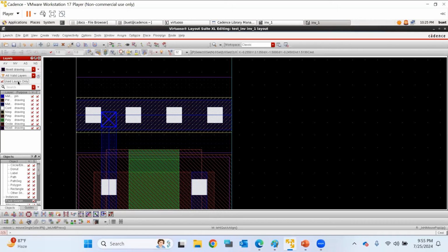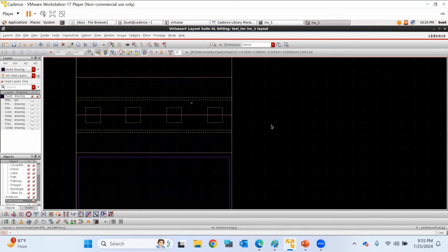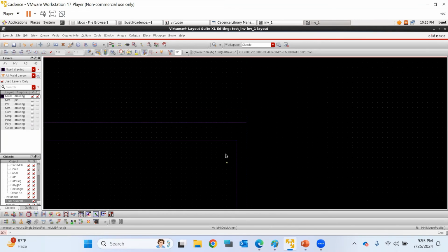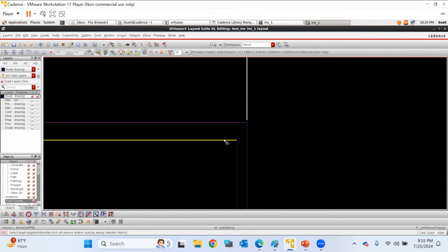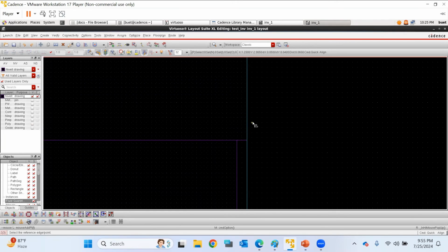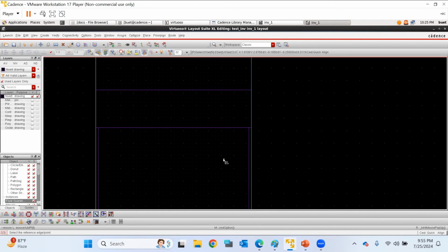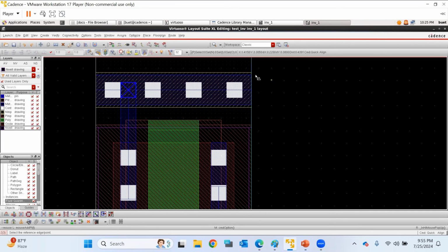Okay, I will be putting NV, only turning on the N well. To turn on the N well, see, the N well to N well, here is a distance. It should not be there. Either you follow the maximum distance thing or you should align it. Otherwise, it will give a DRC error. Now I put all visible. Now it's not visible. Okay.